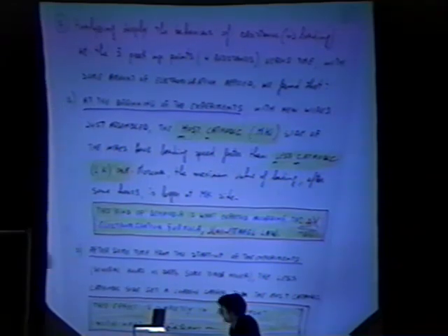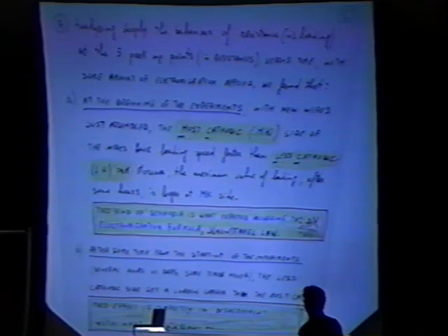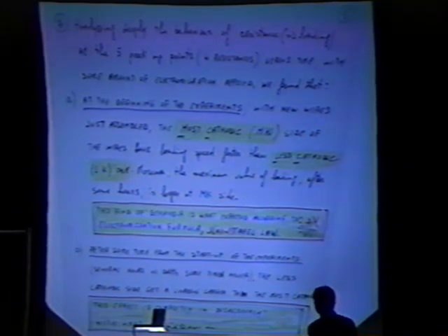So I want to introduce: we had 5 pickup points, meaning 4 resistances, and we found that at the beginning of the experiment, the most cathodic side of the wire always loaded faster and to a higher value than the less cathodic. And this is what is expected, nothing strange. According to the electromigration formula, delta voltage is larger, because we have a larger current on the most cathodic.